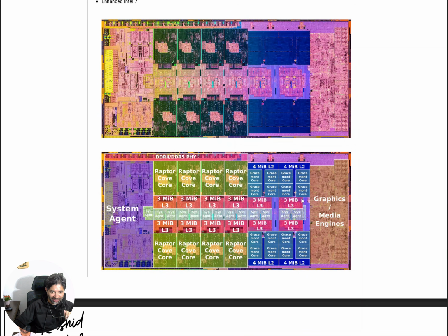And you are doing timing of this entire thing. On every node you want to calculate delay, you want to make sure no node is missed. If one is missed, you really want to know why it's missed. Should it miss or not? And on all those flip-flops all over the design, you want to calculate setup and hold time. And you want to be sure it has to work, right?